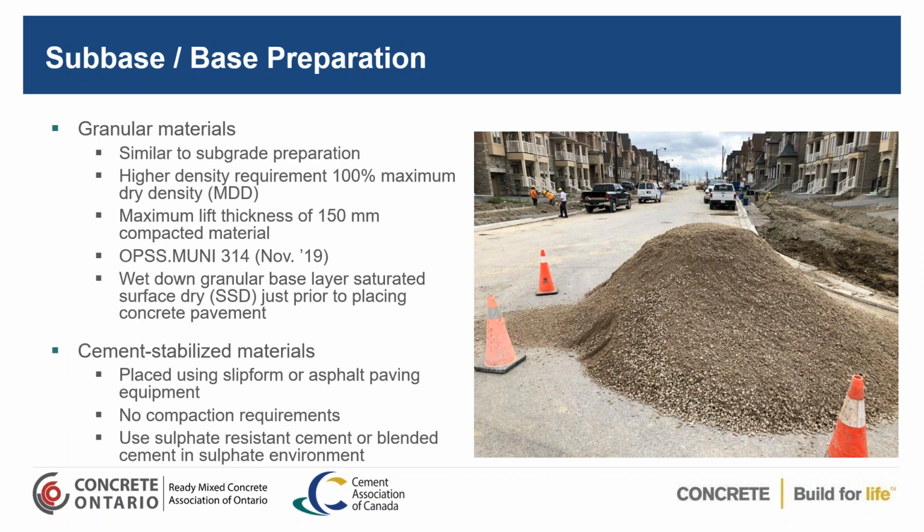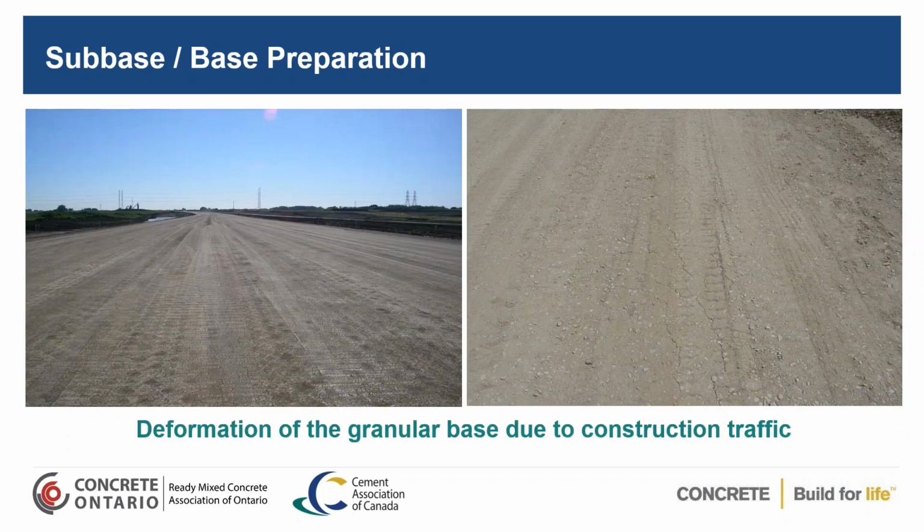Now, again, you can actually stabilize this material with cement. It's a common practice when you're doing airport operations, but not something that you see a lot in municipalities. It is done when you're using a chip seal type thing, but when you're using concrete in the municipal environment, you don't usually see a lot of cement modified soils being used in the aggregate side.